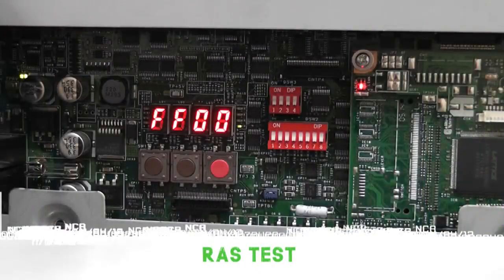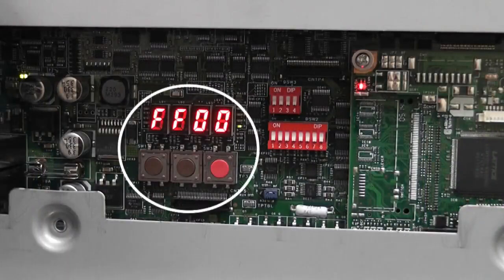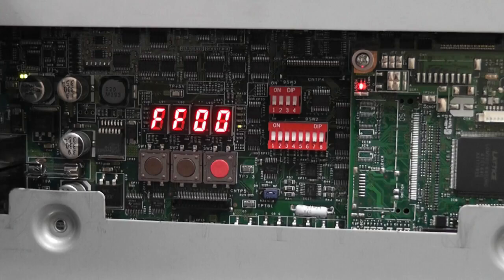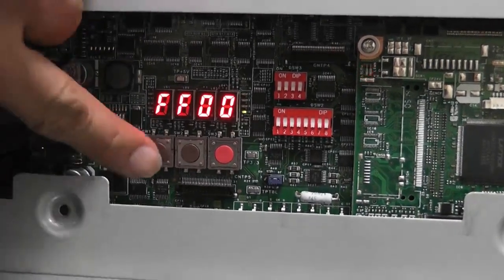The BRM supports the RAS system test through 4 7-segment displays, together with 3 push buttons in the upper module control board. The buttons are named SW1, SW2, and SW3 from left to right. To start the RAS test, press SW1.